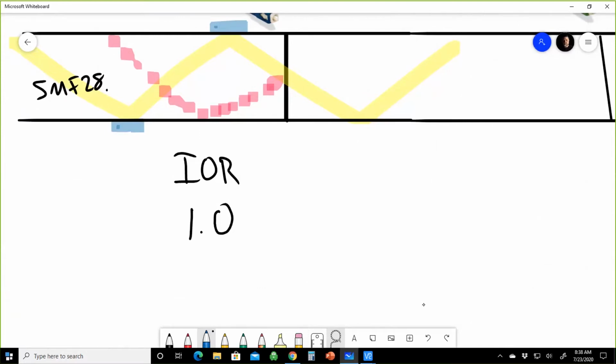So if you're doing long haul fiber, you might have something like Leaf. You might have TrueWave. And again, these are brand names. I'm using these because this is typically the naming that you would use in the field, right? People don't say G.652D. Now they'll say SMF28. They'll say things like AllWave, Leaf, TrueWave. I mean, there's a lot of different types of fibers. These are the brand names.